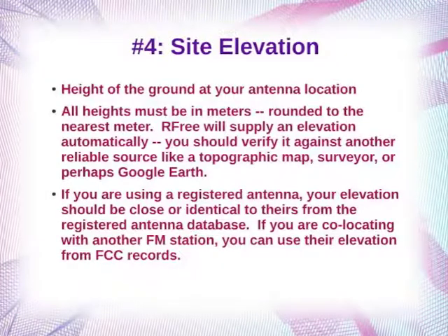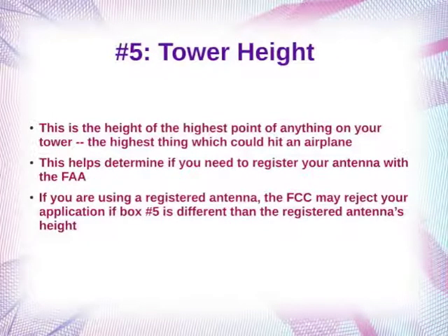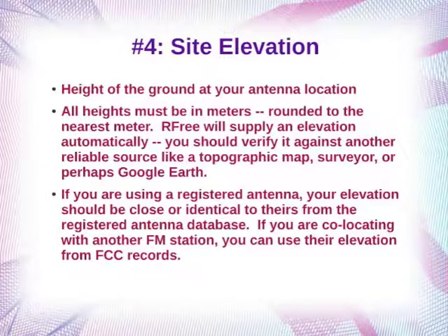So, site elevation. This is the height in meters of your station, your proposed location at the ground level, not the top of a building, for example. Heights must be in meters and rounded to the nearest meter. That's sometimes inconvenient because a meter is a pretty big unit of measure. And like it says here, if you're using a registered antenna, make sure that the registration record for that antenna and what you put on this form is the same.